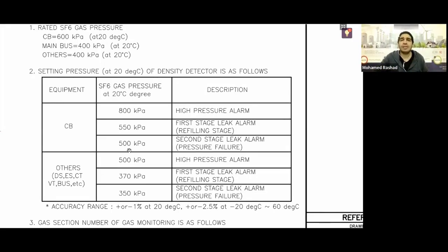For every other part, whether it's a disconnect knife switch or a ground knife switch, it's just the terminals only. As for the circuit breaker, if you have low stage 1, you will find it blocks the closing of the circuit breaker, but allows tripping. However, low stage 2 blocks both tripping and closing, not allowing the breaker to close if it's open, or open if it's closed. And we will see this within our control circuits.